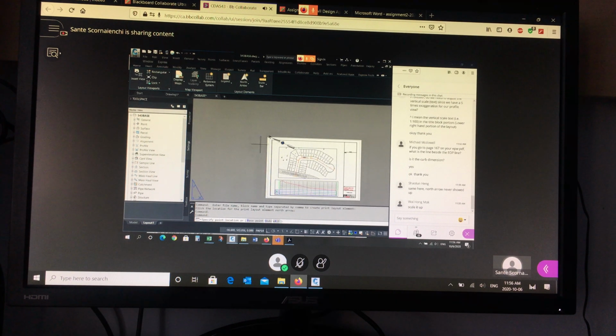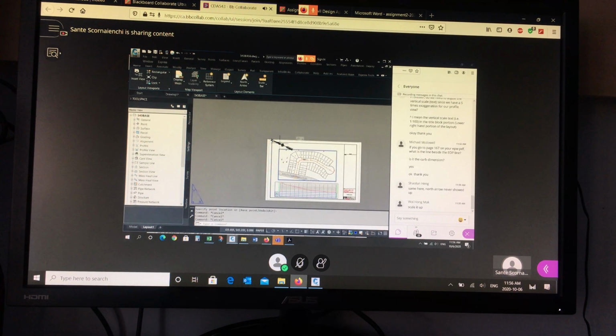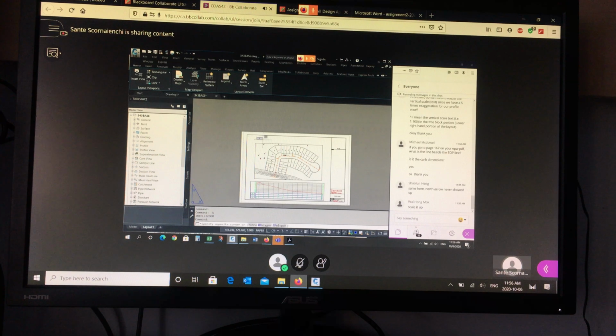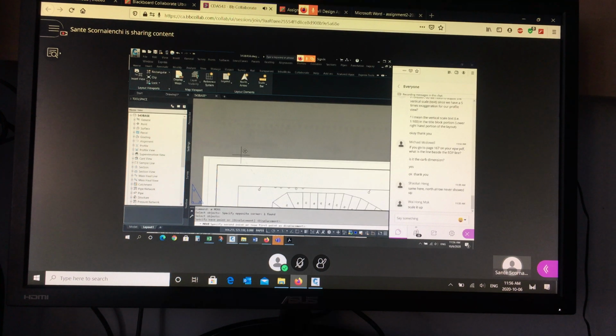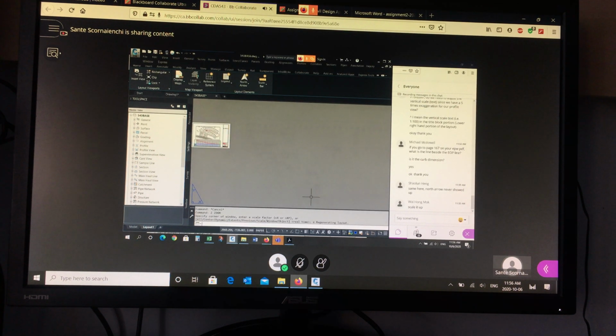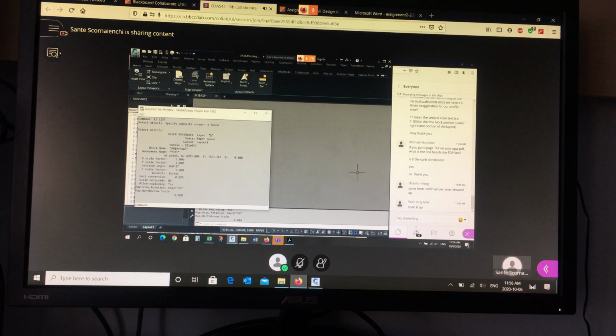If you don't see it, it might be not in the frame. So it might be off here somewhere. If I zoom extents and you see that effect, it means it's out here somewhere. That may be the other problem. And the third issue is if it's on layer 0, which it should be by default.